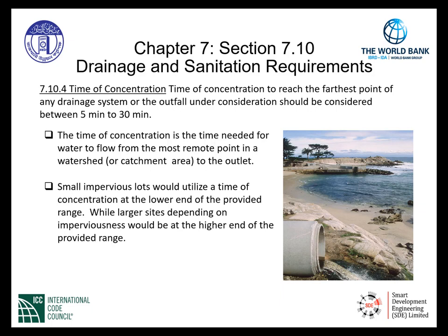Time of concentration is indicated in section 7.10.4. Time of concentration to reach the farthest point of any drainage system or the outfall under consideration should be considered between 5 minutes to 30 minutes.